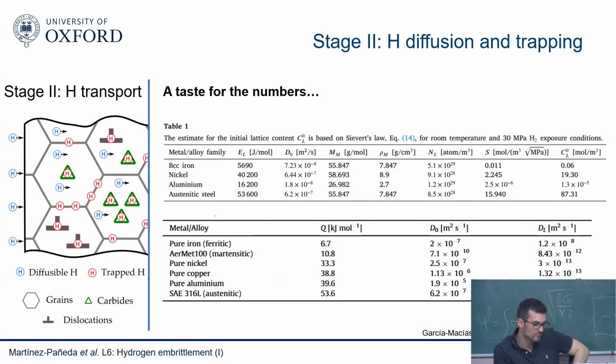And I mean, I don't think there's a clear understanding of why this necessarily happens. There could be arguments that even if you do experiments at very, very low strain rates, whereby somehow your diffusivity gets compensated, you are dealing with steady state scenarios. You also see this. What is a steady state at the macro scale might not be, of course, what is a steady state at the micro scale. So that also can matter. But in general, it's not as simple as just saying, oh, hydrogen will move much faster, so you get more hydrogen accumulation, because we also see it at very, very low or constant load experiments and things like this. So I think that's an aspect of discussion, but it is what we observe.